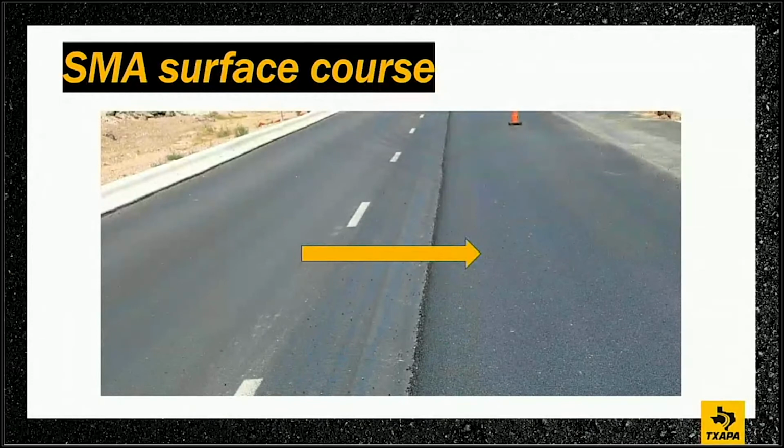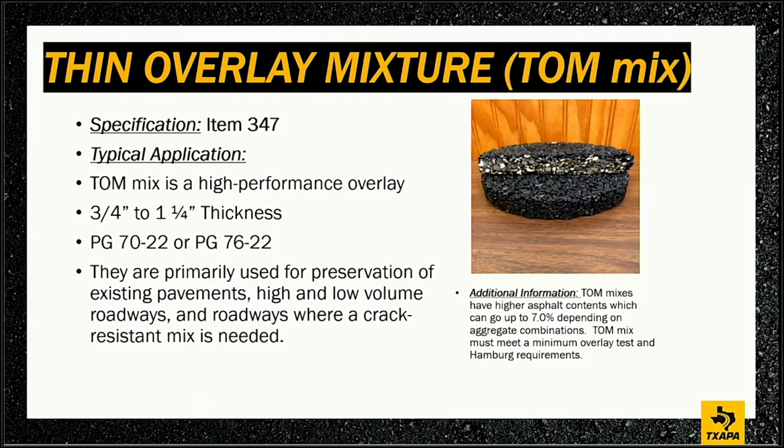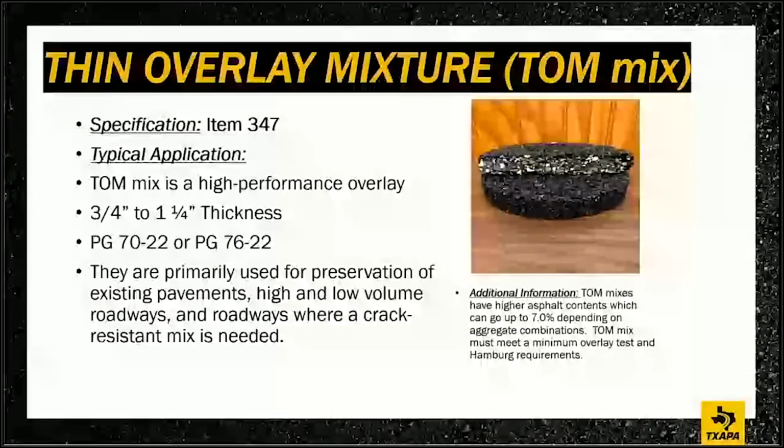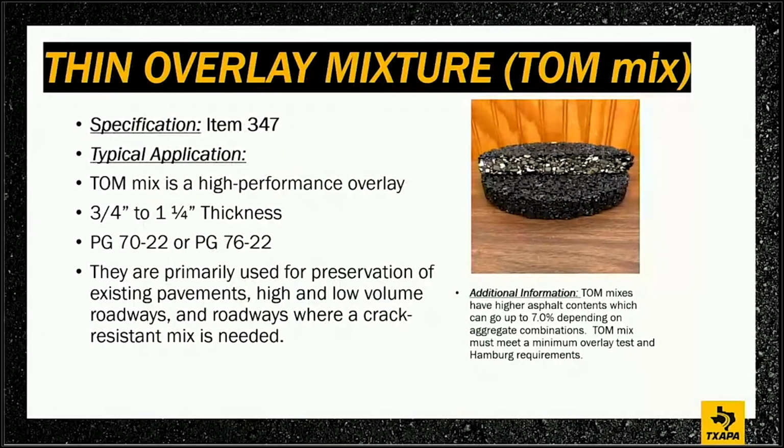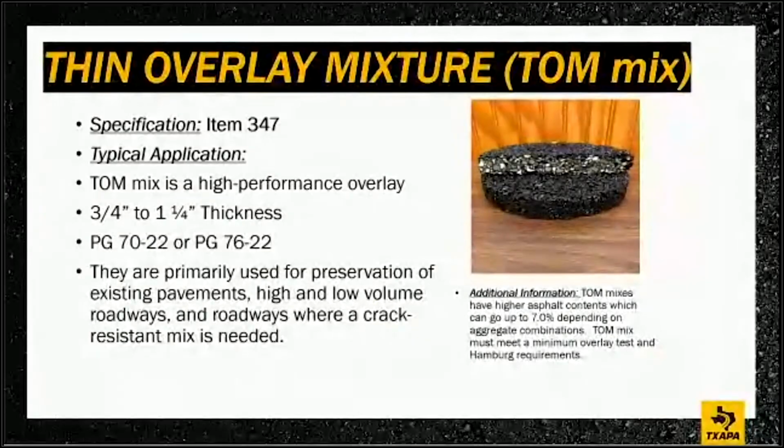If I find a joint in the wheel path, you are not winning an award, okay? You do not honor the pavement, in my opinion. Think about it: we're loading on the weakest link, and we certainly don't want to do that. So we always want to make sure our wheel paths are in a sound structural area, and you want to offset those joints so they're out of that. Not just because you can win a pavement award, but so the pavement can perform properly.